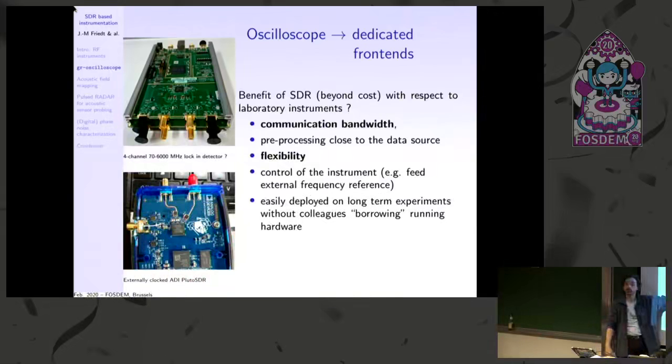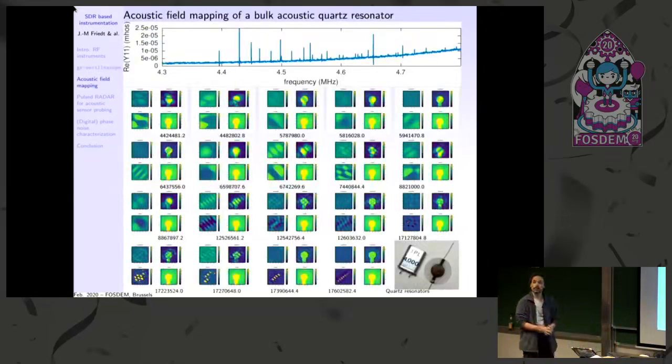If I take just an oscilloscope, or actually any Rohde and Schwarz instrument, well, actually Rohde and Schwarz is not a good example, because I can feed it with a 10 megahertz external clock. But an oscilloscope, I've never seen an oscilloscope to which I could give an external clock to clock my A-to-D converters. So here is an example of a practical demonstration. I'm not the guy doing the frequency transfer.